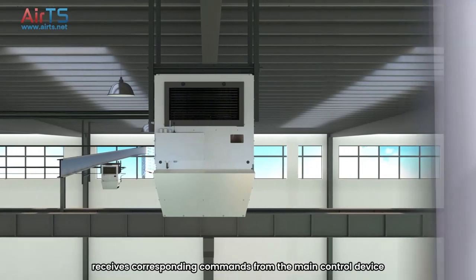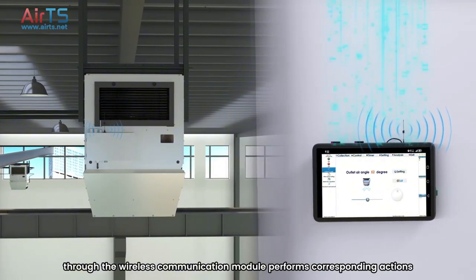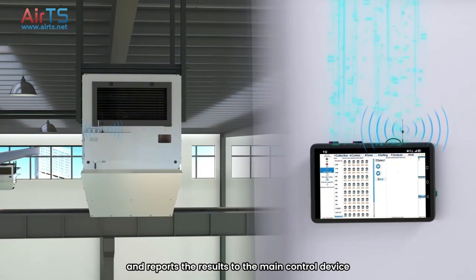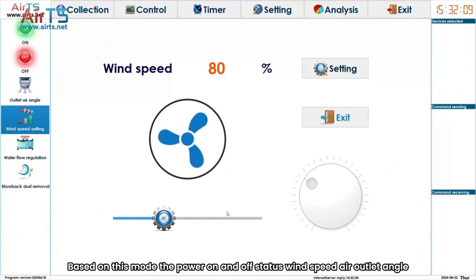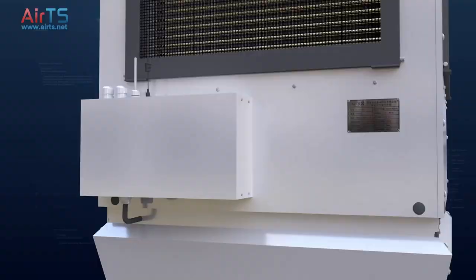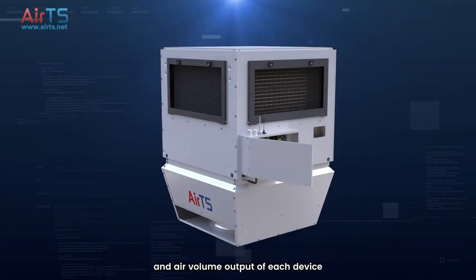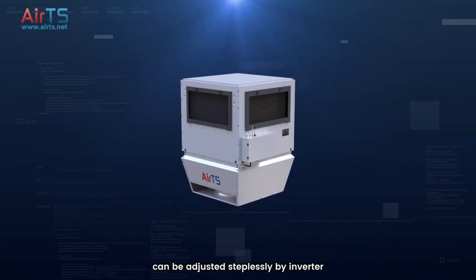The main control board receives corresponding commands from the main control device through the wireless communication module, performs corresponding actions, and reports the results to the main control device. Based on this mode, the power on and off status, wind speed, air outlet angle, and other status of each device can be set independently and arbitrarily, truly achieving single machine, single control. There is a frequency converter in the control box, and the cooling capacity and air volume output of each device can be adjusted steplessly by inverter.